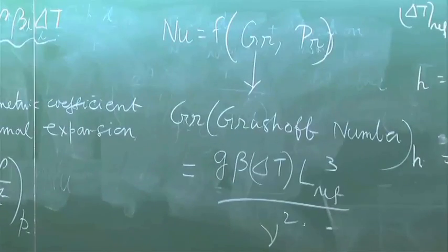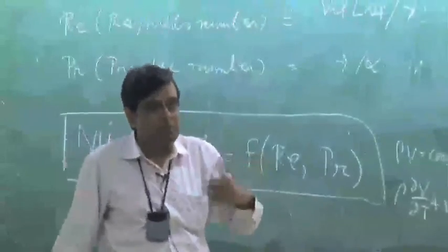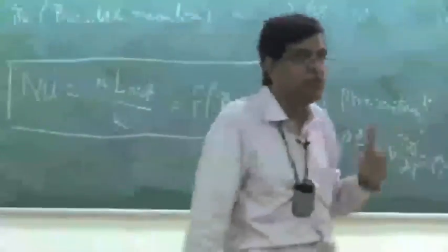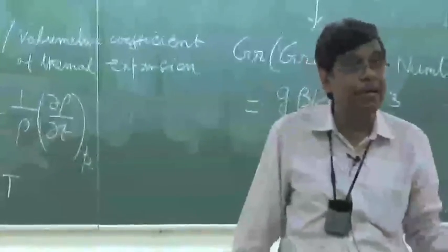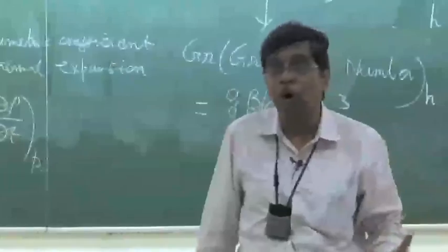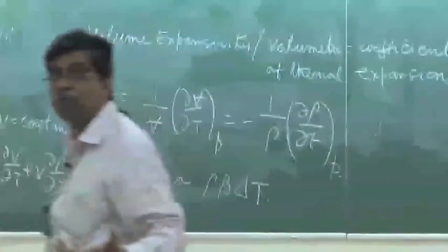So the physical significance of Reynolds number, you know, it is proportional to the ratio of inertia to viscous force. So Reynolds number implies the inertia to viscous force, and it represents the dynamic similarity of the flows governed by inertia force, viscous force, and pressure force.